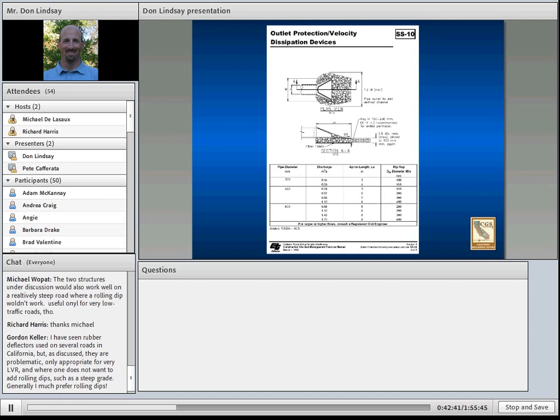The diagram uses the pipe diameter and the discharge as input parameters. Notice that the riprap is placed on top of a layer of geosynthetic fabric, and the thickness of the rock is about 1.5 times the maximum stone size. FHWA presents similar design methods based on the critical shear stress and the exit velocity of water as it leaves the pipe, which is similar to this that Caltrans developed.